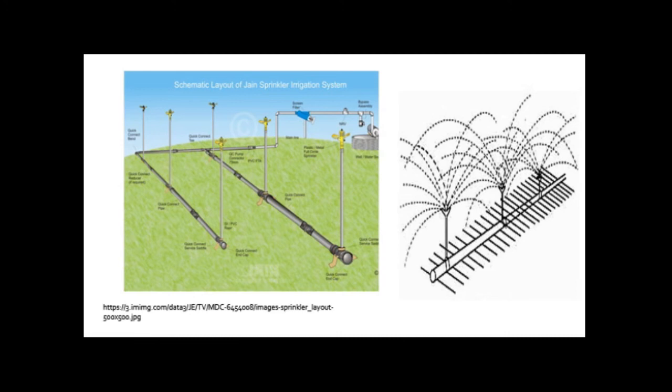Some of the few disadvantages of sprinkler irrigation are that pressure head and sediment-free water are required, so it is not suitable for plain land. Likewise, the initial cost is relatively high and regular operation is required due to frequent clogging of the system. Similarly, it doesn't suit paddy crop. Likewise, areas with high air flow are affected during the operation. Furthermore, due to circular spraying of water, there are chances of over irrigation and no irrigation in some areas.